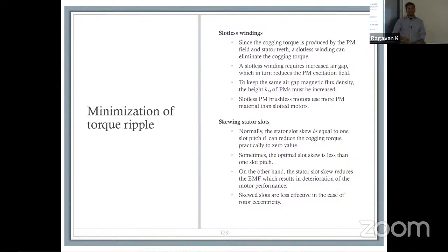One is electromagnetically, you have to make sure you are in the right place. Second is your laminations are not going to be identical, which now creates a question of, is it possible to basically stamp them out? Can you get the same lamination at a reasonable cost? If it was all laser cut, easy enough, or reasonably easy enough, right? So you cannot just skew them because you want to. There are manufacturing challenges you do have to consider and you have to overcome.